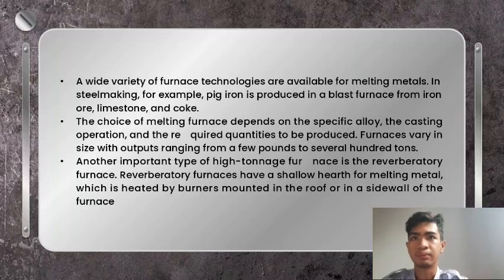For low melting point alloys, such as zinc or lead, for example, temperature may only need to reach as high as 400 degrees Celsius. Fuel sources such as propane or natural gas are usually used to achieve this low temperature. For high melting point alloys such as steel or nickel-based alloys, the furnace may be designed to achieve temperatures well in excess of 1650 degrees Celsius. Electricity is typically used to reach this high temperature.